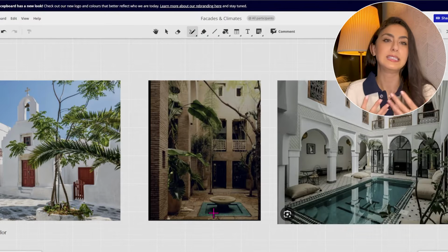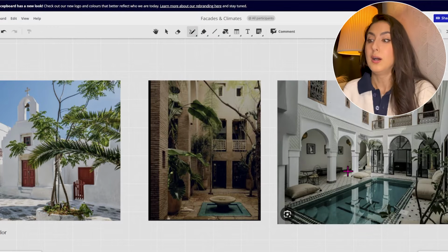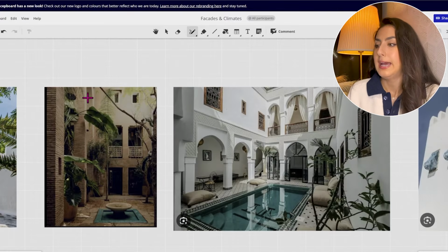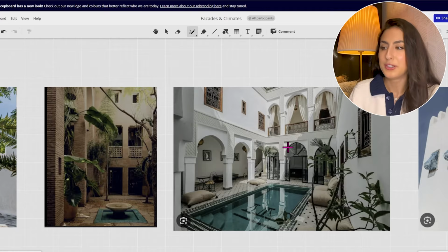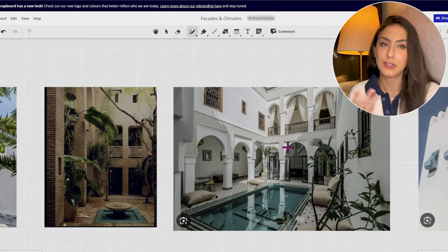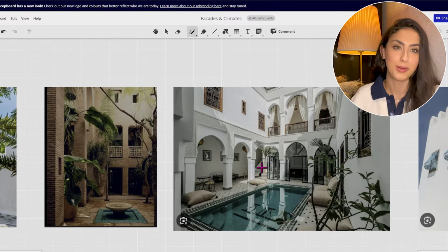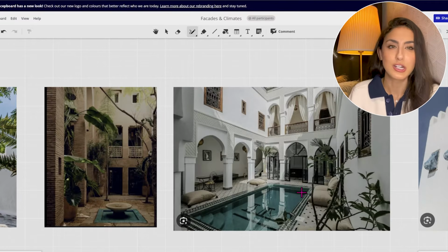And a bonus point, if you add a little fountain there, you can have this evaporative cooling, because the air is really dry in this hot arid dry climate. So that evaporative cooling is going to create a little bit of coolness. Is that the word? If that's a word, I don't know. Coolness to the space. And this is, now it's more of a Riyadh looking, vacation hotel thing, but it really does serve a purpose. And it's fascinating to me how architecture throughout the years, they just learned how to survive in such a harsh climate.